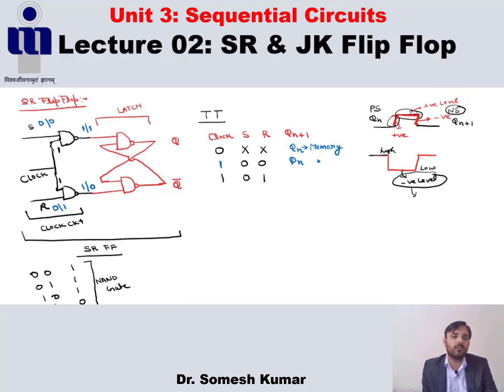If one input of this NAND gate is 0, then the output becomes always 1. And if this 1 is given to here, then it becomes 0. Fine. So here the output becomes 0. If the output is 0, then this state is called the reset, meaning the output is reset to 0.